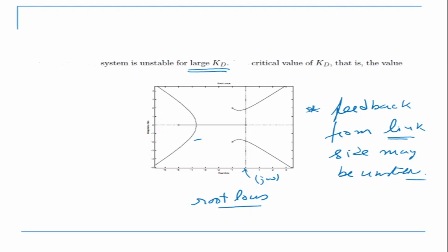Okay, so today first we looked at control of a single joint. Then we looked at series elastic actuators, where we are trying to introduce stiffness in a joint, and then we are trying to control the motor such that I get a desired position on the other side. And as I was saying, when we come to biped locomotion, we'll see that these kinds of actuators are used these days, essentially because we need to absorb the kind of impact that is coming.